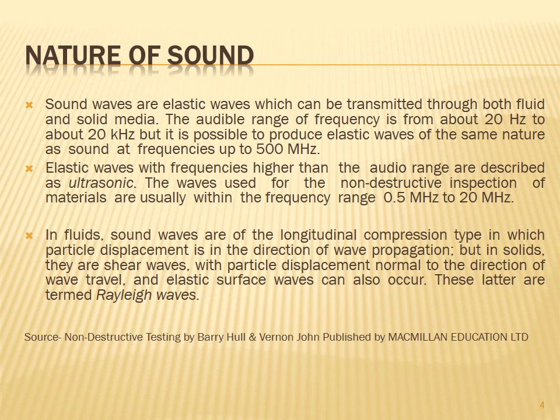The waves used for the non-destructive inspection or testing of material are usually within the frequency range of 0.5 MHz to 20 MHz. So we are using 0.5 MHz to 20 MHz whenever we are using an ultrasonic inspection technique. So we talked about the nature of sound.